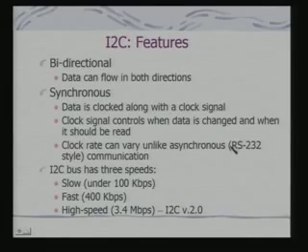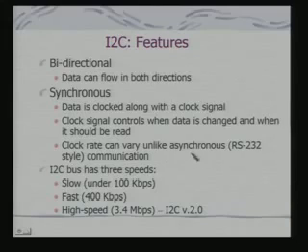In an asynchronous communication like RS-232C, you have to have a fixed clock rate because you are sampling the bits, that means you are finding out whether there is a start of transmission or not at the clock intervals. But since here the clock is being transmitted along with the data, the clock determines the valid data transition. So there may be a change in the clock speed as well.